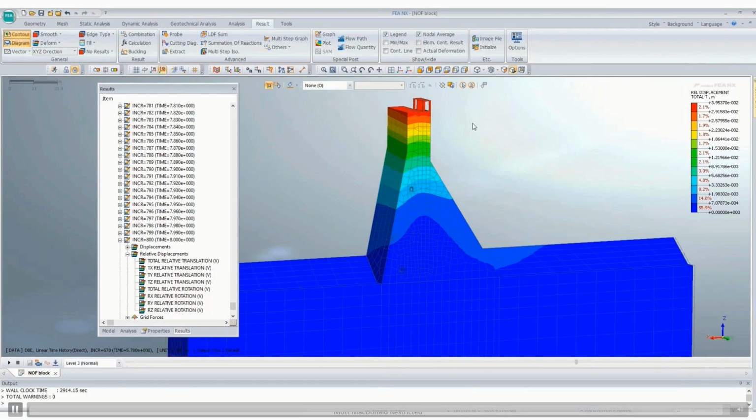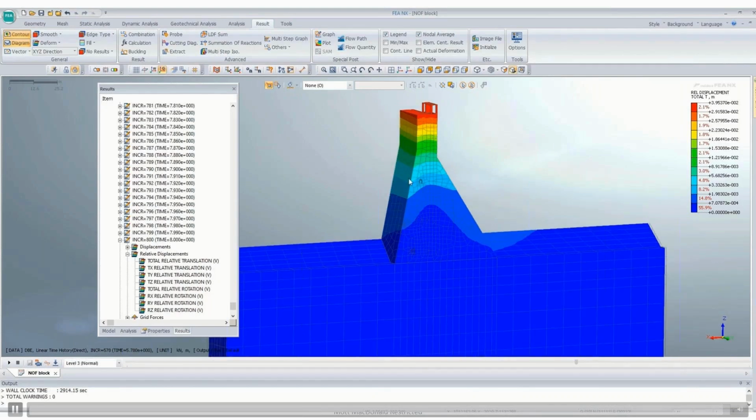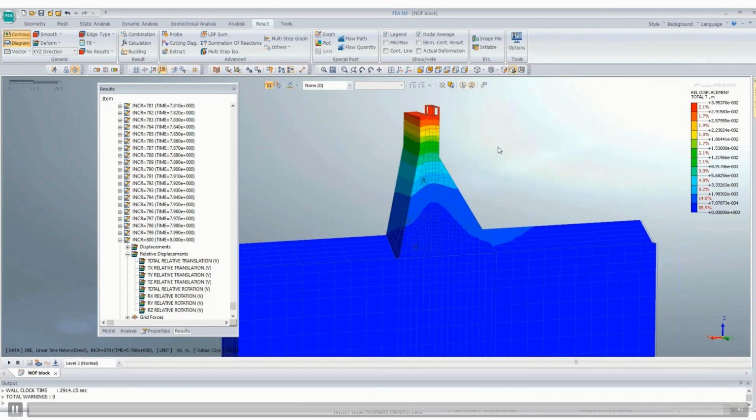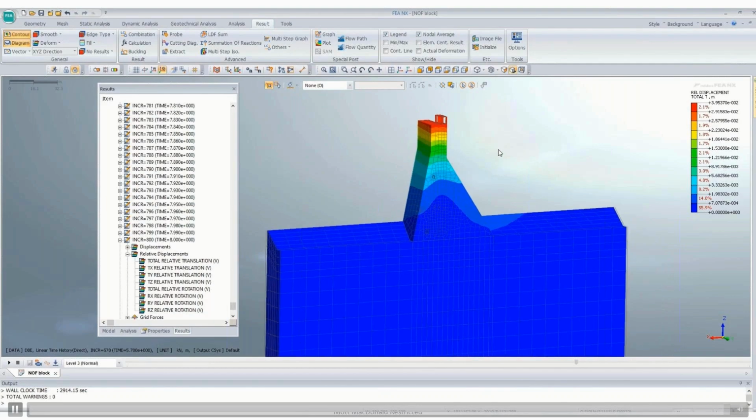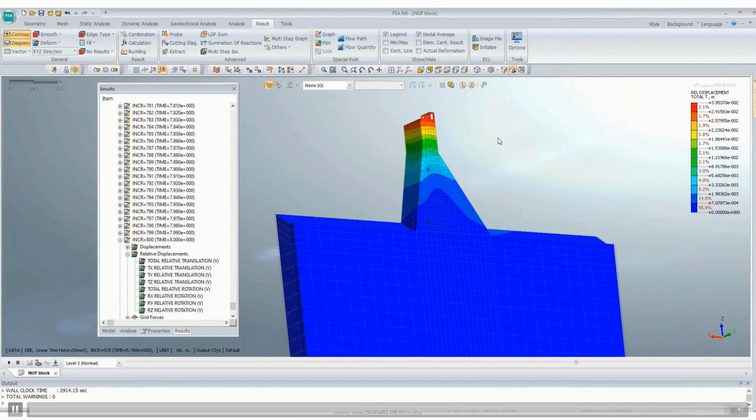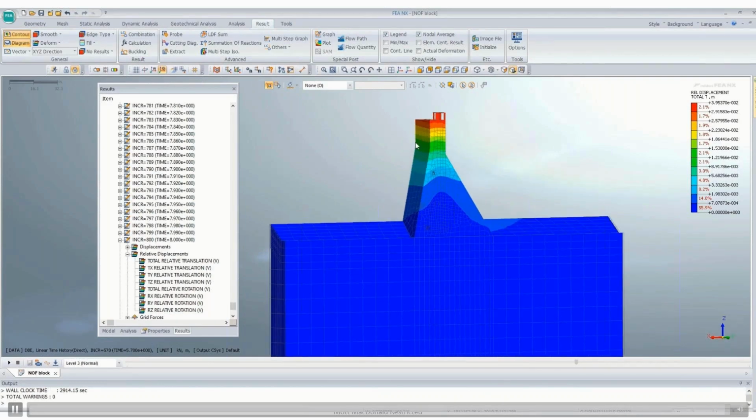Okay, we'll check here also, and we will check a few nodes on the upstream face of the dam, whether the reinforcement exceeds the DCR of 1 or 2, DCR of 1 for DB case. For that we have to analyze it with the other load cases. Say for D case, we have to analyze it with the self weight. For E case, normal operating case, we have to analyze it for all the normal operating loads. Okay, we'll do it in the next session. We will conclude this in the next session.